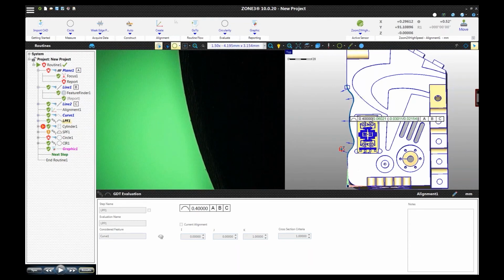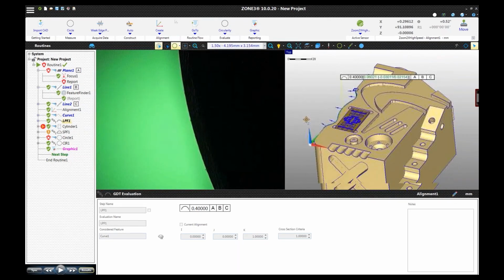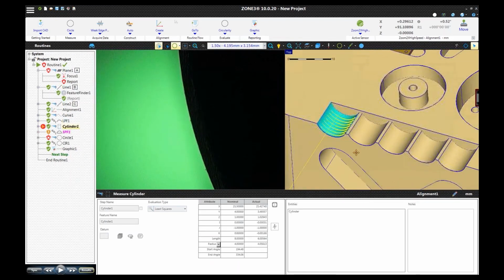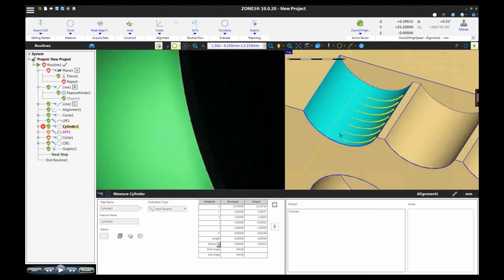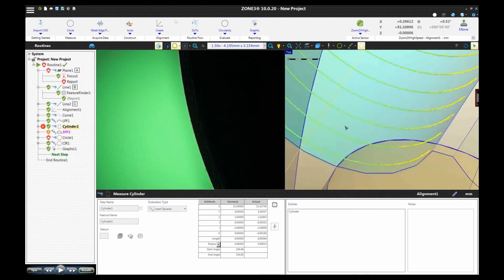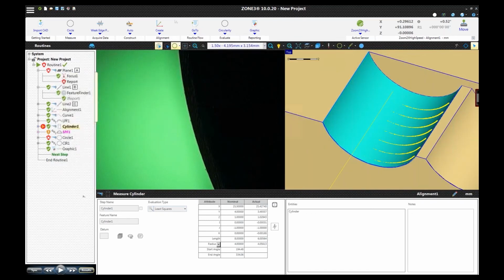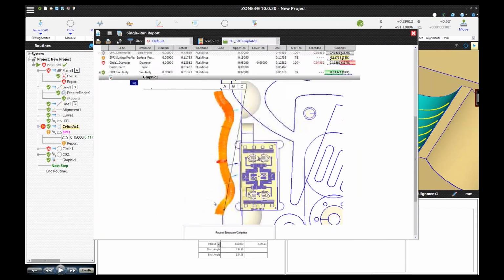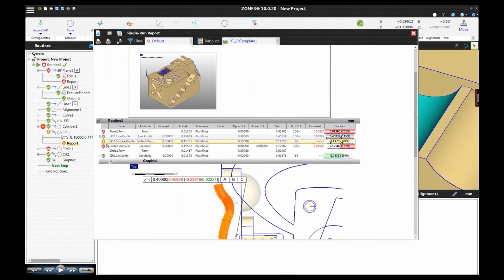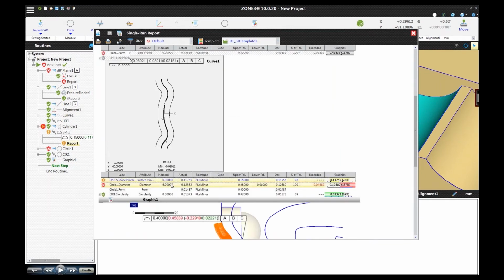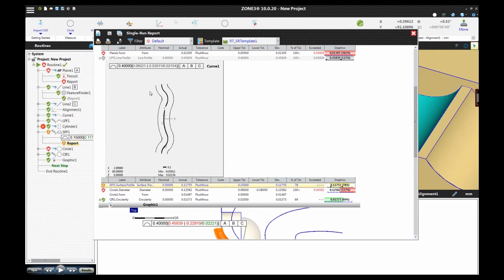Okay, so the other way the graphical reporting could be handy is, again, for this profile of a cylinder measurement. Now I've got all these points here, and it's quite a few. If I look closely, those are all laser scans that I took on the cylinder, and then I did a profile of a surface measurement. Now, if I go back to my results, even if I'm outputting this profile of a surface, which I am, I'm not going to see in there one of these little whisker plots, because it'd be really difficult to show the deviations if they're not 2-dimensional.